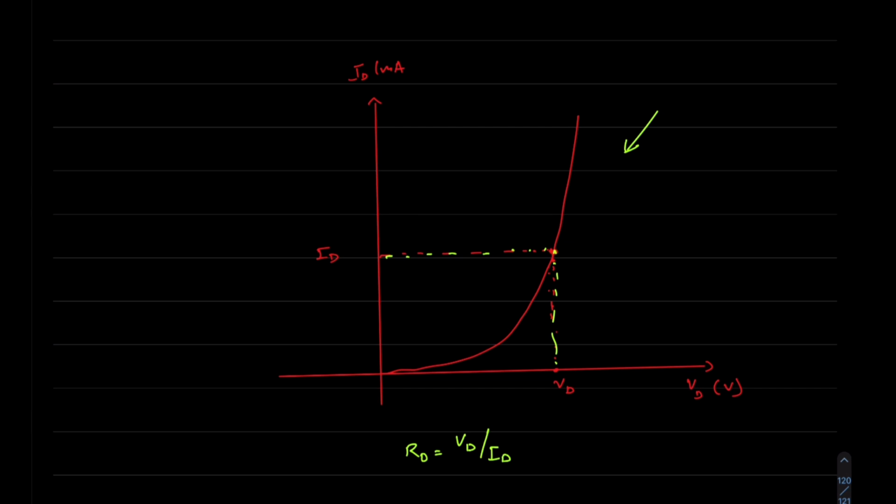Now if we talk about dynamic resistance, let me clear it out a bit. There are two ways to find the dynamic resistance under forward biasing conditions, right? First is to simply get the reverse of the slope, so 1 by slope. How will you find the slope? Well, it'll be given in the graph.